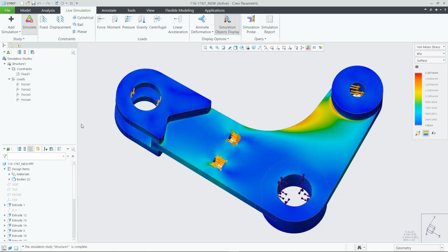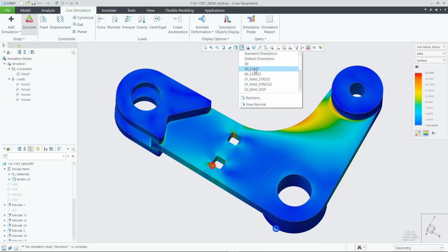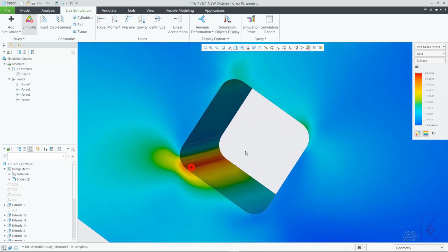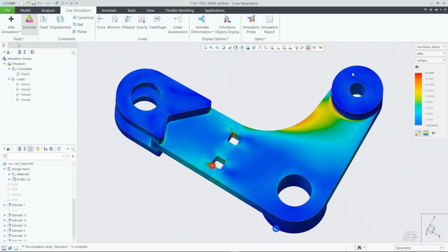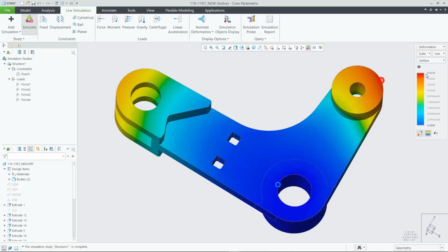Same sort of thing as always. Where are the hot spots? Where's the max deformation? Where's the greatest stress? Look at that. Let's put it in megapascals. That looks good. And say, show me where those high points are. So, yep, they're going to be right in that area there because that's where we're tugging on it. So that's not too surprising, but good to see and good to know exactly what the numbers are going to be in that area. Do the same sort of thing, deformation.